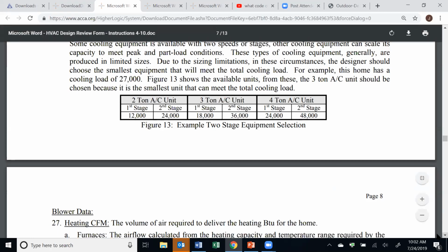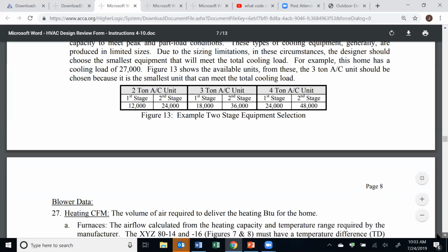They'll come on, cool or heat the space and then stop. And so oversized systems, and that's another reason, going back to the whole 1% and 99% design values, why don't we design for some extreme weather condition? Well, we're trying to minimize that equipment cycling when and where we can within a reasonable limit.